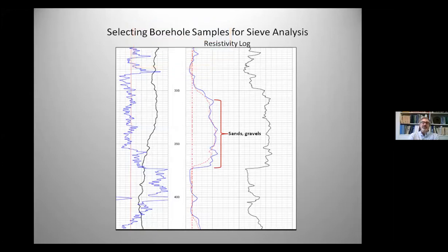So if there's sands and gravels that you've seen in your physical samples coming out, you may start to say, well, this formation is more likely to contain water, as opposed to other type zones that have deflections to the left or have a lower degree of resistivity. These are very tightly packed formations, suggestive of tight grain-to-grain contact situations. So these would be more indicative, say, of silts and clays, and less likely to contain water.